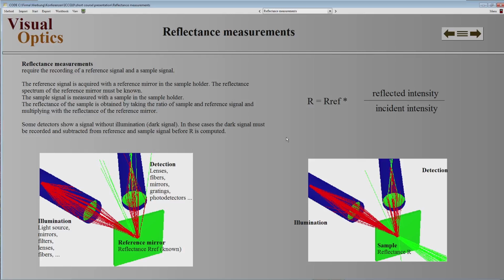If you are not fast enough to move it away, then the next glass will crash into your reference mirror. So what you usually do in the case of reflectance, you move out the whole system to the side, away from the coating line, and do the reference measurement at the site where you have enough time, and then you can move back to the line in order to measure the next glass.